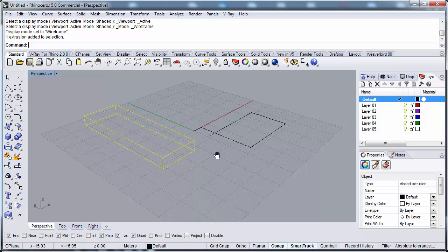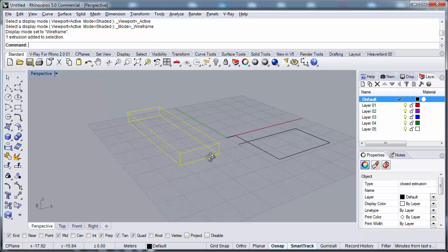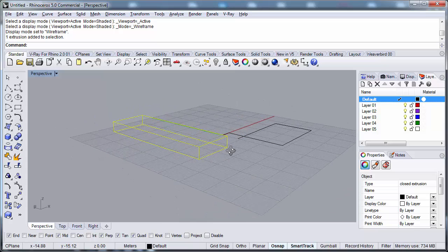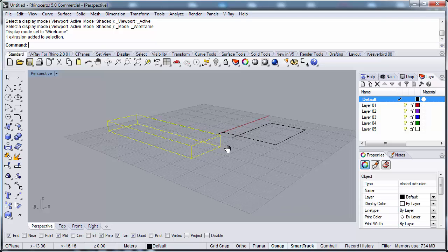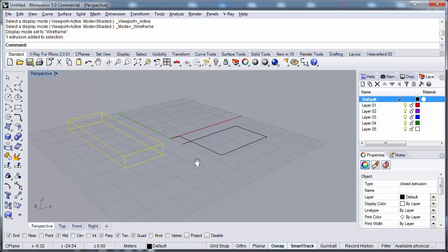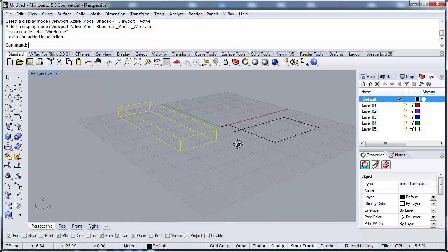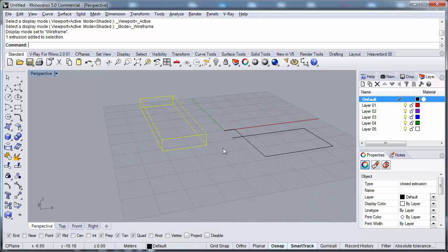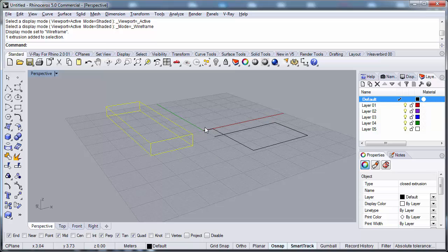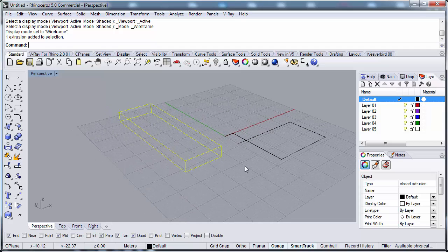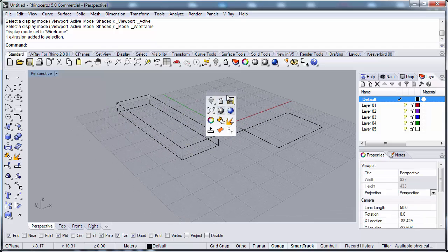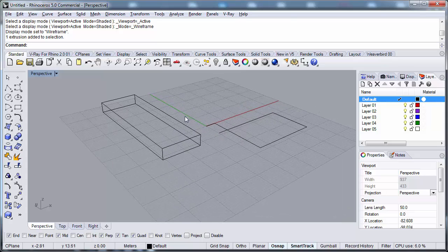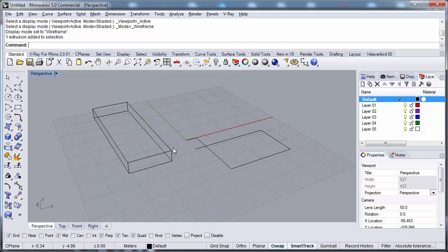Now Rhino has panning on shift and right click, and I can rotate with the right click. So my middle click here is used for this pop-up toolbar where I can put my shortcuts. Great, many people use it, but many people coming from AutoCAD programs hate it. So put the navigation to the middle mouse and forget about this menu.